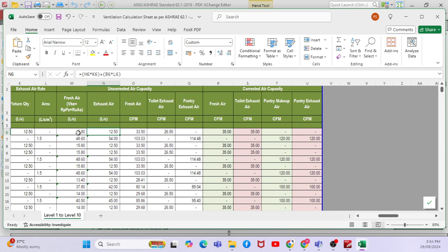I will create a positive pressure where humans live, or where I don't want bad smells taken away from the breathing space. So that particular area I have to create a positive pressure. Where I have to create negative pressure, such as kitchen or pantry, or where I am expecting bad smell, because the smell may spread outside the room, go to the neighbor space and disturb the other people.